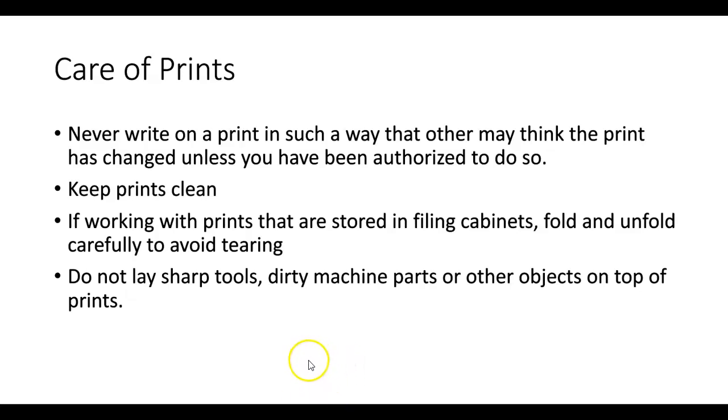On the care side of the prints, make sure that we don't write on a print, so we don't get it dirty. We want to keep it clean. Prints, if they are actual paper copy prints, do get stored in file cabinets. The larger print sizes will get folded and unfolded, so you do want to be careful in that process to make sure that you're maintaining and keeping those prints in good condition as they move about from the factory floor. Likewise, don't lay any sharp tools or dirty machine parts or other objects on top of the print that might cause oil or dirt to get on it and impede the view from the other people that would need to read the print.